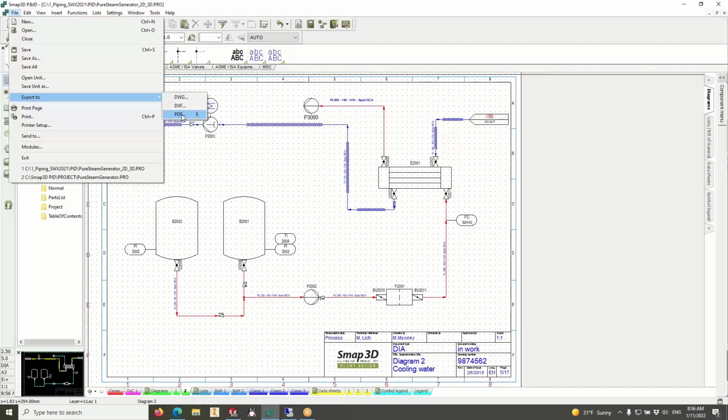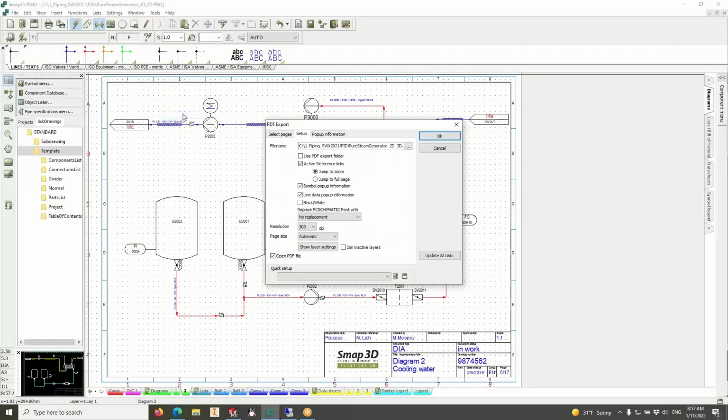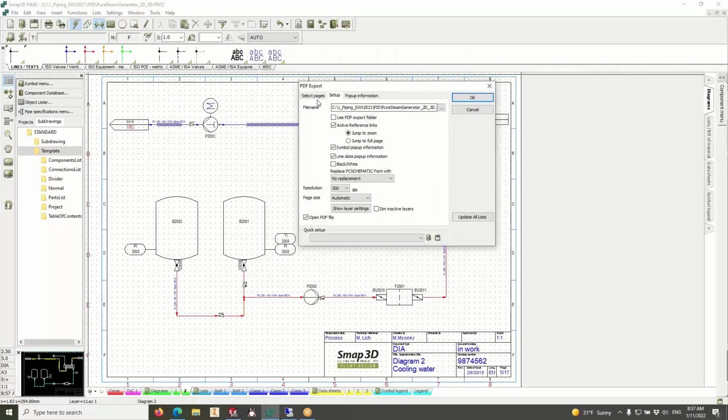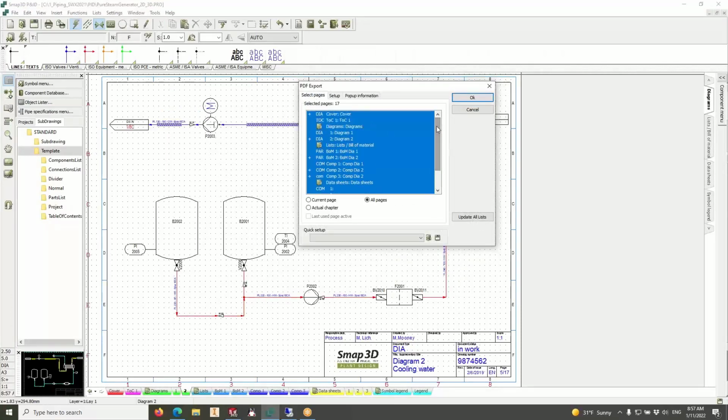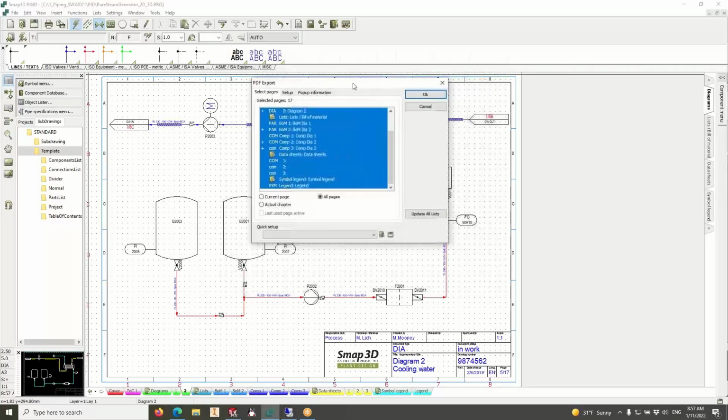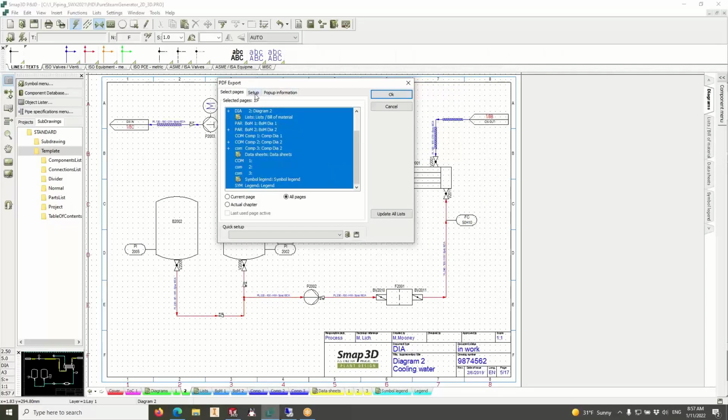But a better communication tool is going to be a PDF, because a DWG and DXF still requires a specialized program to read them. And maybe that specialized program is something as simple as eDrawings. But also they're not secure. People could change them if they had AutoCAD or DraftSight or just pull them into SolidWorks. You could make changes. So your PDF, many good things about that. Anybody with Windows can read a PDF. They don't need a specialized software, and they can view or print only. They can't change things in a PDF.